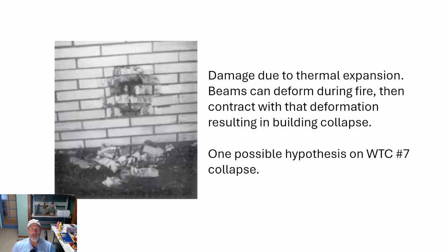And what that did over time is, even though you had fire protected beams, the fire retardant on the beams, what it does is it delays heat transfer, but it doesn't prevent it. So if you expose a 1 hour rated beam to a fire over 8 hours, you're going to basically have the same kind of effect as if it had no fire rating at all.